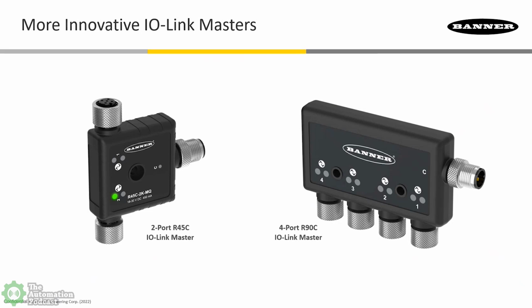These are 2 of our other IO-Link masters that play really nicely with the one I was showing on the previous slide, which has EtherNet/IP, Modbus TCP, and Profinet coming out. So you're using the Modbus port to expand how many IO-Link devices you can connect on one Ethernet drop, whether it be EtherNet/IP, Profinet, whatever. Wow. Yeah, it's really cool because then you could have multiple IO-Link masters. You could tee into multiple of these IO-Link masters on that Modbus RTU port I was showing before, and that's been used quite a bit.